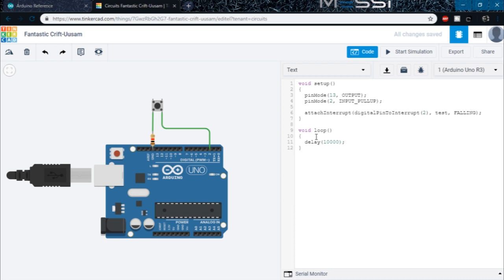Okay, now if we put a lot of delay then our loop is freezed and our loop is not running. Okay, but still I will be able to detect this switch press, and that is the work of the interrupt. Interrupt has always the highest priority.